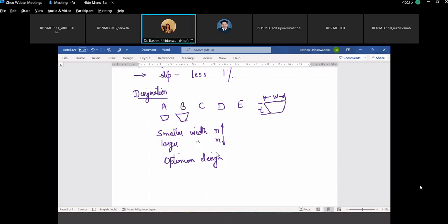And what happens if out of 4 belts, one belt undergoes wear and tear? If one of them is worn out, with wear and tear, its length would increase, and you cannot replace a single belt. You have to replace all the belts.